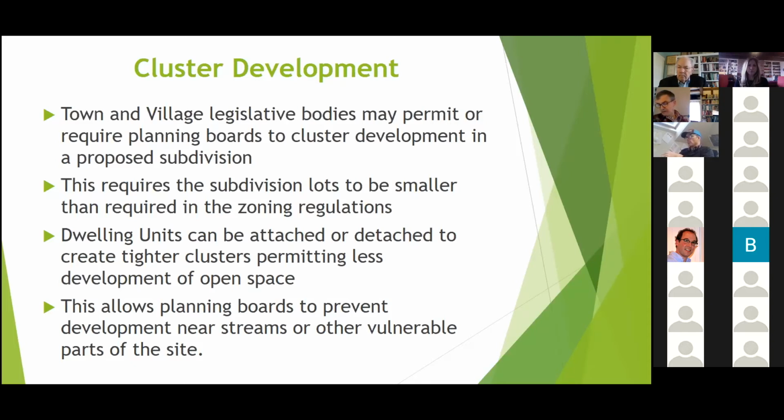Sticking with my own discipline, the groundwater supply side, our model ordinance at least provides some suggestions for trying to keep a cluster subdivision on private infrastructure by looking at directions of groundwater flow. You can count on groundwater flow moving from high to low because water underground does it like on the surface. And so if you have an option to lay out a conservation subdivision with wells all on the uphill side and septics all on the downhill side, you have a potential for a cluster subdivision to be able to advance on individual services, which just leaves maintenance up to the individual property owners. That's not always possible, but that is the guidance that's in the model ordinance.